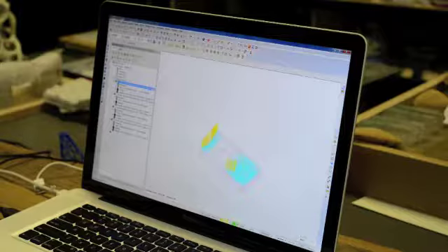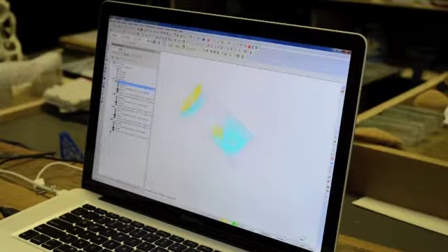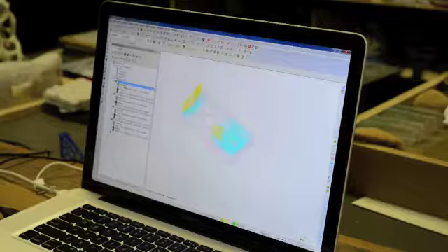Notice it didn't take the stock with it, but this is a really nice feature because otherwise if you just move something, you'd have to go in and reselect all the drive surfaces and containment, yada yada, and that can be extremely time consuming to do. So those are some of the other more nitty-gritty details about working in MasterCAM.